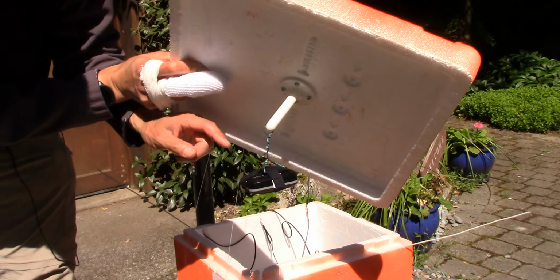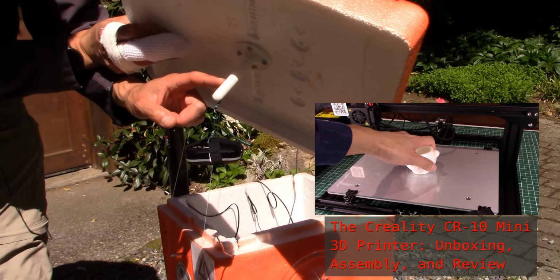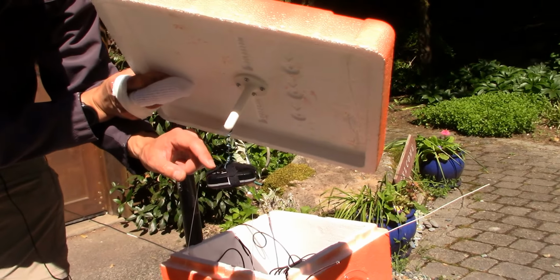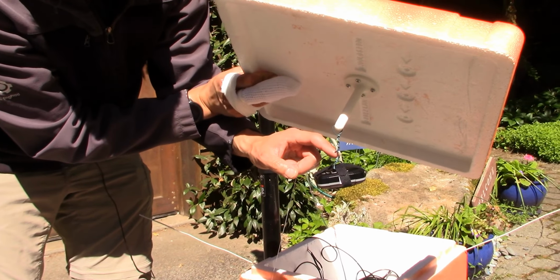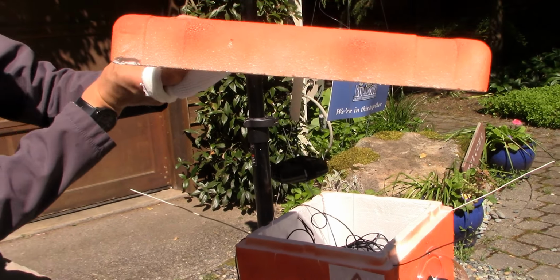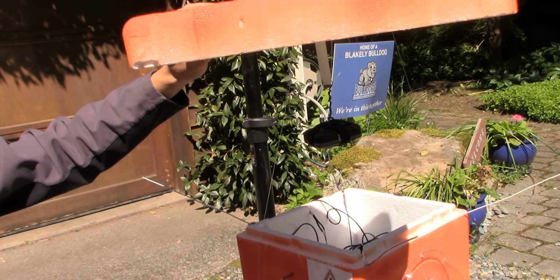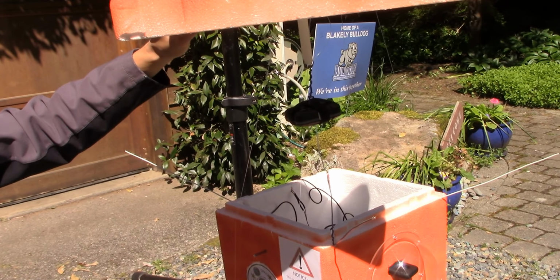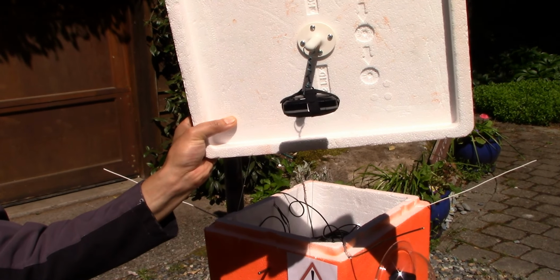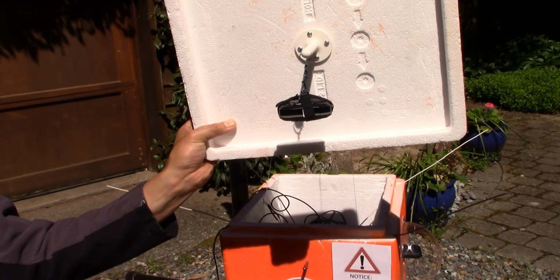So to mitigate that, what we did is we 3D printed this, our poor man's gimbal system. You can see all this is doing is suspending the spot trace unit on a kind of flexible little twist tie system. So basically, if the payload box lands straight up and down in the nominal configuration, it's no problem. The spot trace unit is in the proper orientation. If it lands on its side, gravity is just going to allow this thing to drag the spot trace and still keep it in the proper orientation.